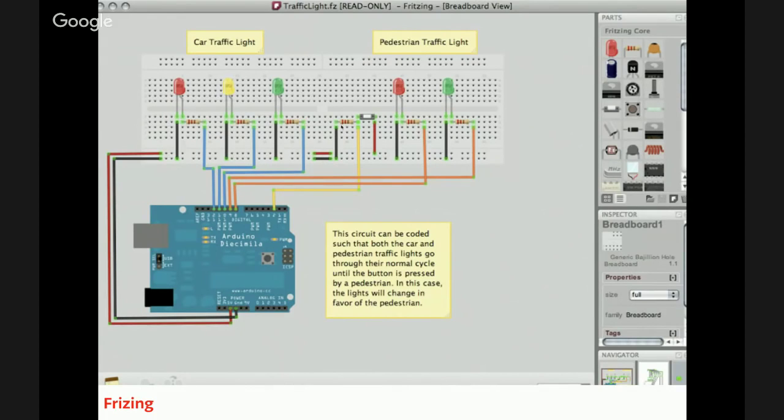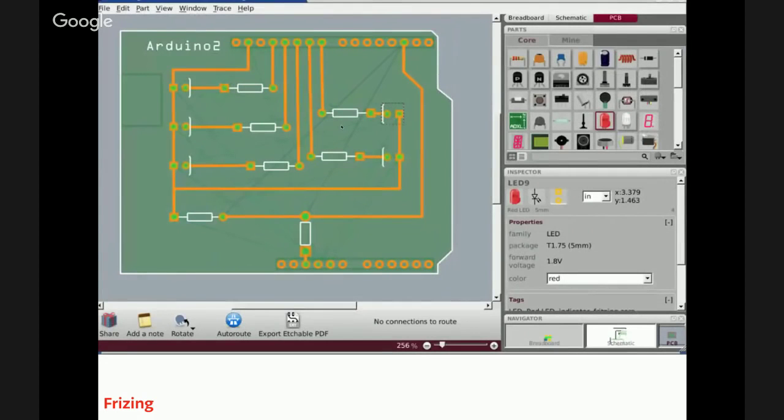So Fritzing, for example, is a tool that allows you to capture a circuit you build on a breadboard. And when you draw it on a breadboard, it extracts automatically the schematic diagram, which can be complex for a beginner. And it also allows you to design printed circuit boards, which you can send to a factory with a click, and you get back the PCB. So this is a PCB generated by that diagram you saw before. Again, these kinds of tools that guide beginners to the point of making a PCB without being a hardcore engineer are an interesting tool for us.